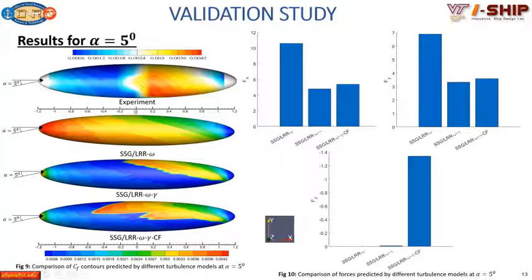The cross-flow is sort of captured, but again, it's a little upstream, and the windward side transition is not really captured in this case. As in the other cases, the streamwise transition model is able to capture some of the transition here, but apart from that, it's a fairly poor approximation.